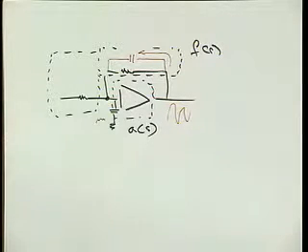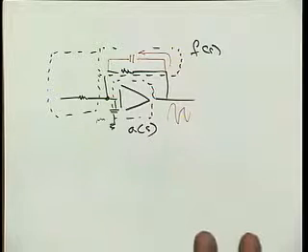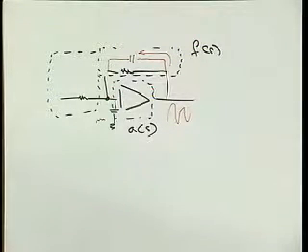But anyways, sometimes over all of that we forget that the real reason why we need to cover feedback as a special case is that we need to be aware to check for T of S. T of S is nothing that we are fundamentally interested in, right? What we want to know is the closed-loop gain of the circuit. Well, looking at the closed-loop gain of a feedback circuit doesn't tell you anything about its stability, right?